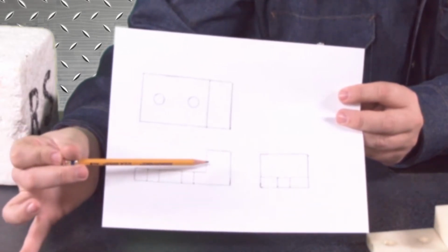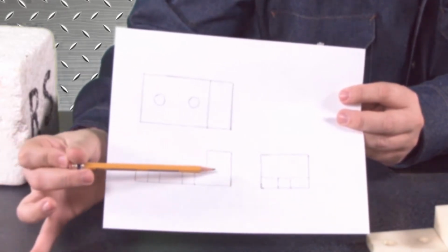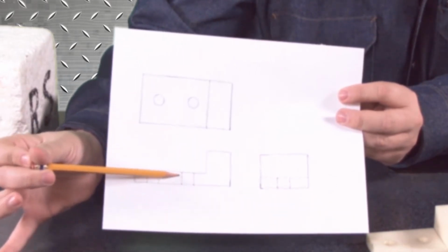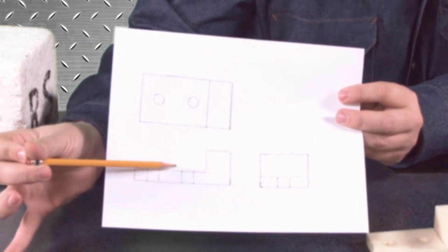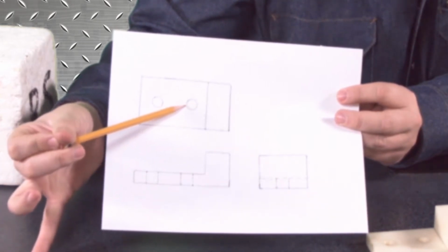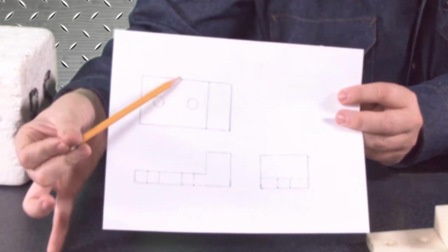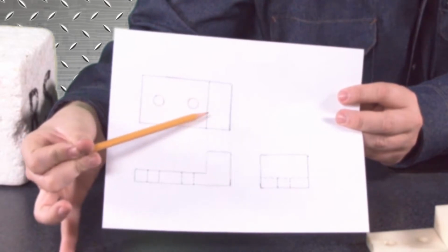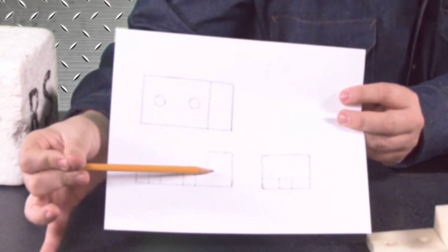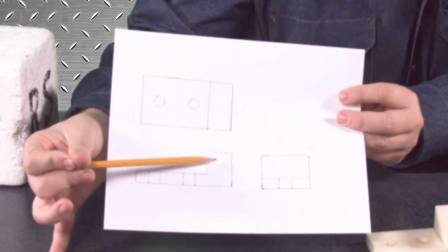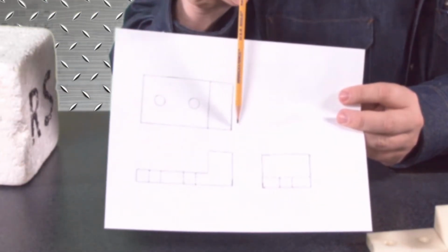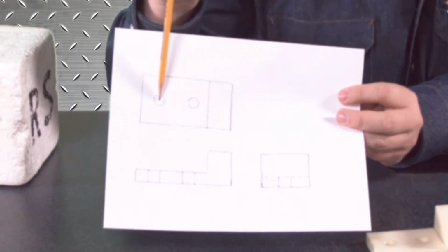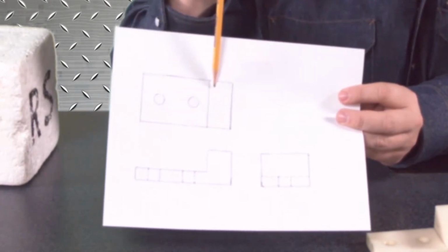So to have that front view here, our object lines are what we visibly see, and then our hidden lines are what we don't see. And those hidden lines are representing the edges right there. Then from our top view, you see we have this object line going across here, and it's letting us know that this part has this extension off of it up here to the side. So instead of it just being a plain rectangle all the way around, we can see our holes that'll be put into it. And then you also see another line here.